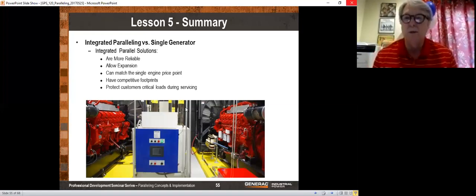and bring in rentals. Now, what you're doing is very typical of emergency systems, and it was one of those things that I said you can avoid if you go with parallel generators. But if you need that, then of course it makes perfect sense. What problems will occur here? Well, you need to worry about grounding. That's kind of an issue.